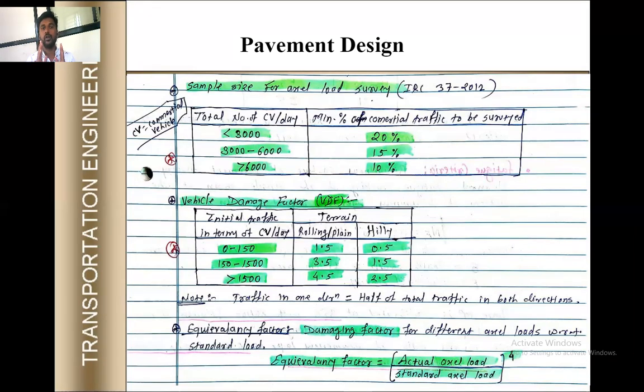Because as per government criteria, for different kinds of vehicles, different loading limits are prescribed. We have to check random commercial vehicles to see whether they are traveling within the required norms. Because if they travel with a higher loading than designed, then our design calculation will fail.